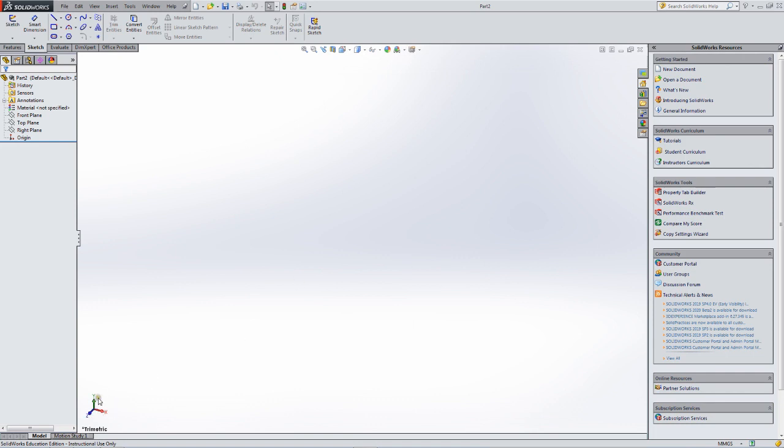We do see the coordinate system, and that's important to us because this shows us what SolidWorks thinks is a front view. In fact, if you go up here to the little view selector and take a front view, you'll see what happens down there. We're looking at the X and Y coordinates, or axes, the XY plane, from the positive Z direction, and that's what SolidWorks calls a front view.